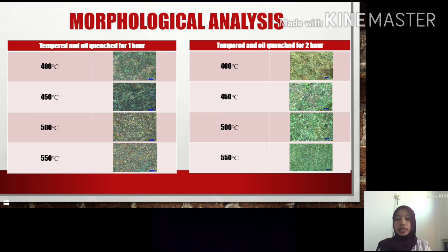However, the grain sizes differ depending on the quenching medium. The overall grain size of the oil quenched and tempered sample is much coarser than the water quenched and tempered sample, as the rapid cooling medium, which is water, gives the finest and smaller grain size compared to oil.